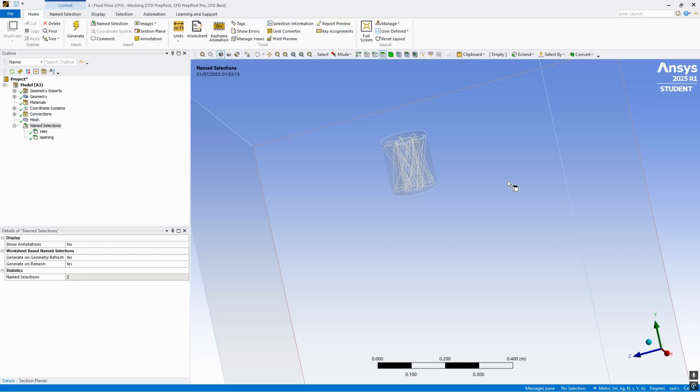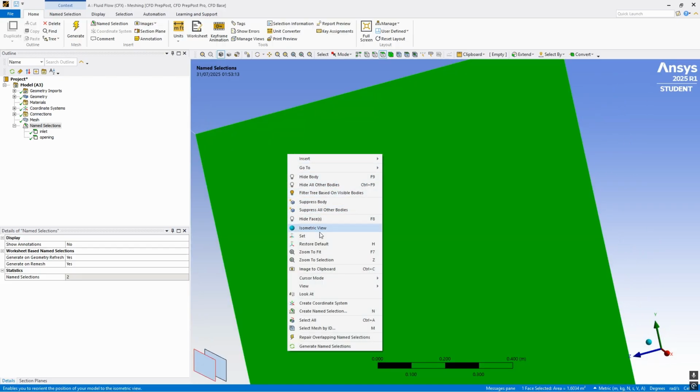And in order to define that, we are going to do named selections on the outer and the inner part of the rotating domain. So the outer part of the rotating domain that touches the stationary domain will be named separately from the inside part of the same part, so that in the setup part we can individually select interfaces and define them. You are going to understand what I mean in a bit, but let's try to name them separately now.